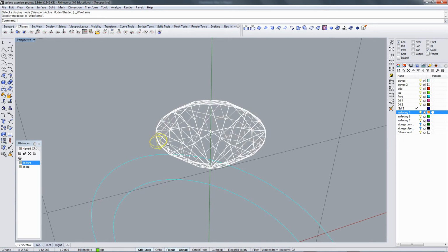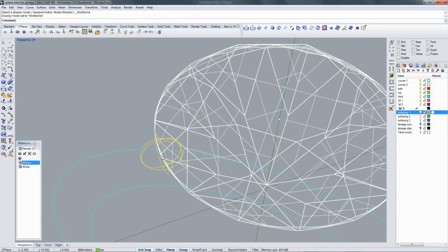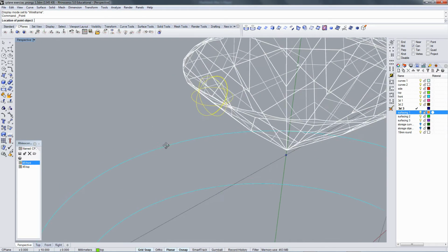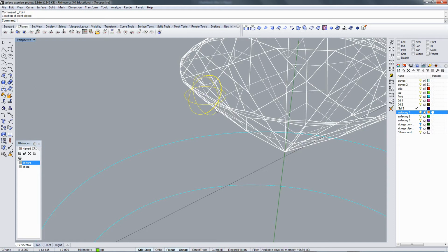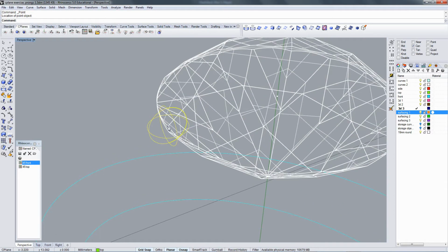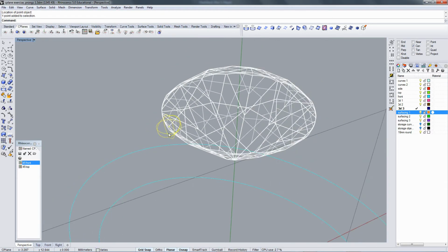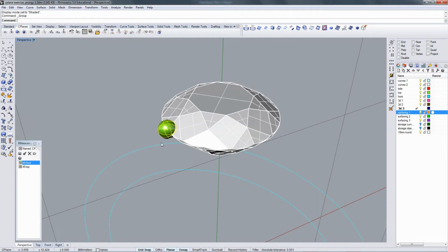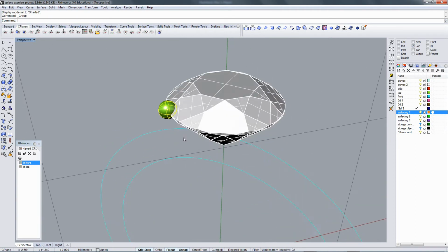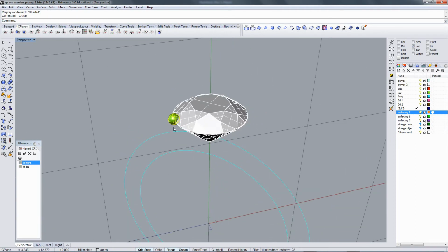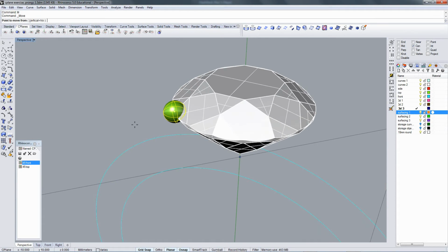This bead, which I put in position, is to indicate the location and size of our prong, which is a 1mm prong. I'm going to put a point in the center of that for reference. Go ahead and group those together. I want to move this bead away from the stone to where it is barely biting into the girdle.